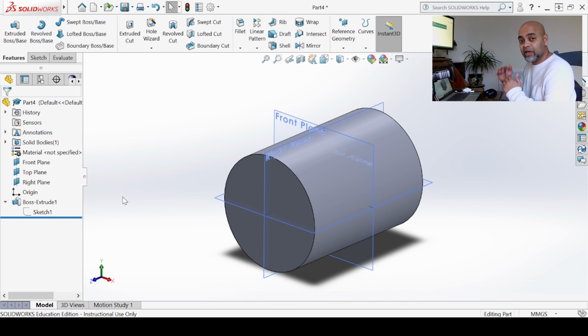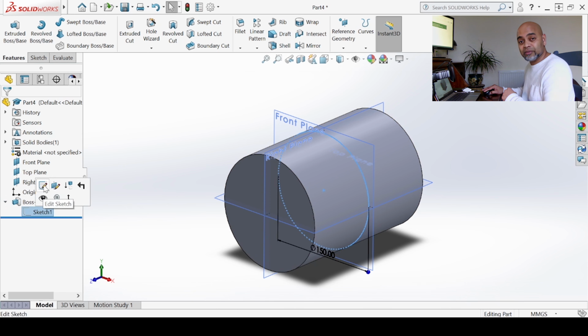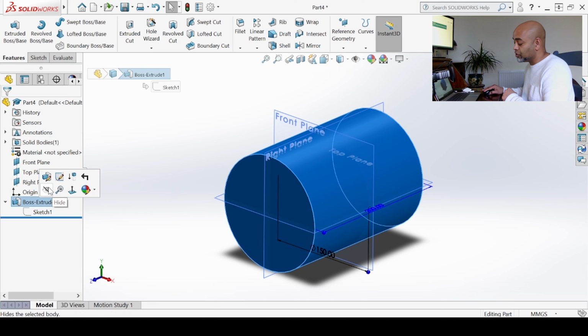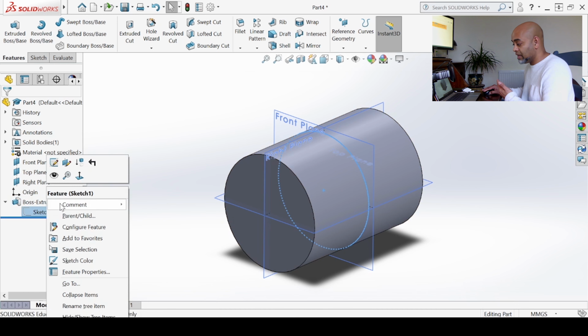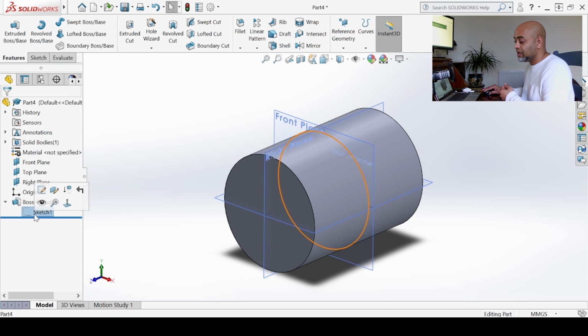Okay, and you need to break it down into the 2D dimensions and the additional dimension, and whichever one you are willing to change. For instance, if you wanted to edit the cross section of your cylinder, all you have to do is go into that chevron, select that sketch, and go into edit sketch, the first option on the left hand side. Once again, it's exactly the same place. And if you wanted to edit the feature extent, you would go into edit feature right here. Both of them are obtained by either right click and editing, or just by select and edit.